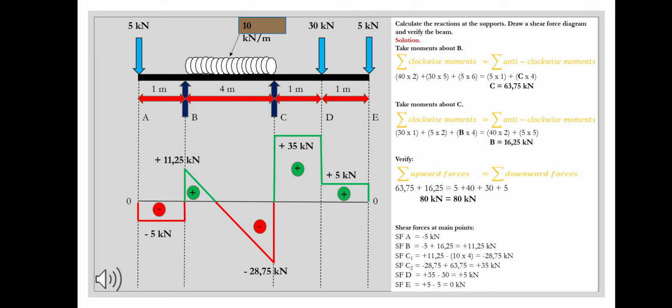Before you start drawing a shear force diagram, remove the point load converted from UDL and put back the UDL to its original position with its original magnitude.